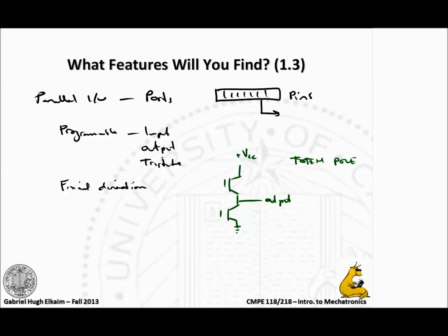And what this means is it will pull it high or pull it low on both sides. It will force it to one or the other depending on which one of these turns off. And there's often something like that goes on the other side of it to make sure it's always doing one side or the other. And these days these are always FETs, no longer transistors. You get better performance and they go faster.